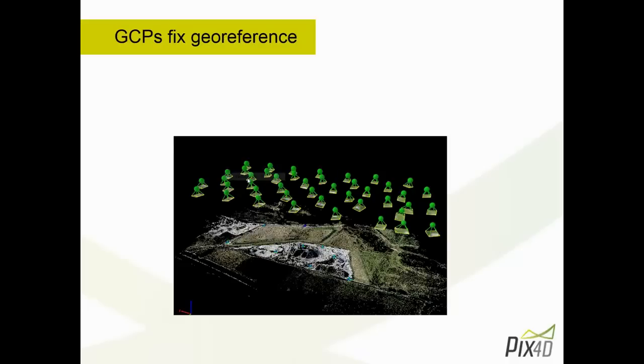So that's actually the real reason for introducing ground control points: it's much easier to use a high quality GPS surveying tool on the ground than in the air. And the good news is that you only need 3 measurements on the ground to define the whole transformation between the relative space and the real world. These 3 measurements you will do on the ground will define the scale, meters or feet, will define the orientation, to put things properly, and will also define the position. So that's really where the GCPs are useful.